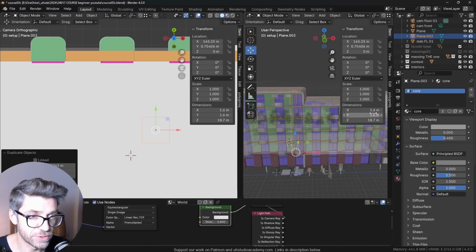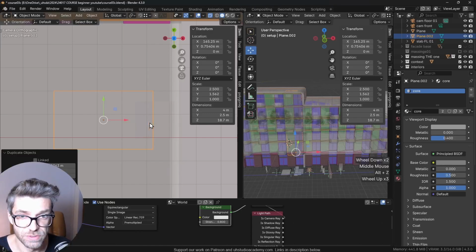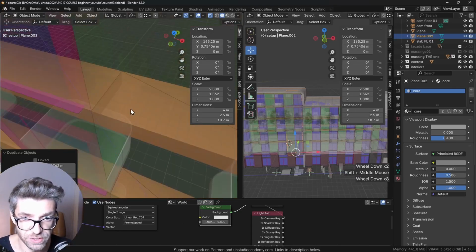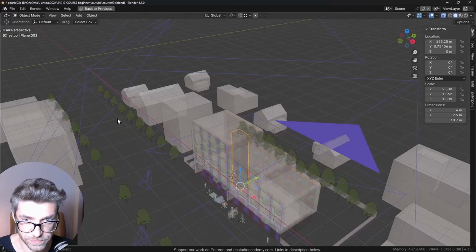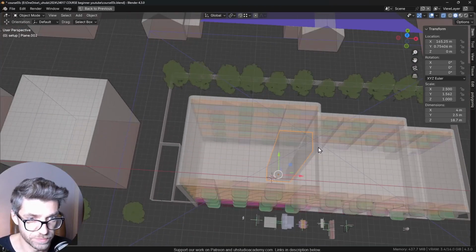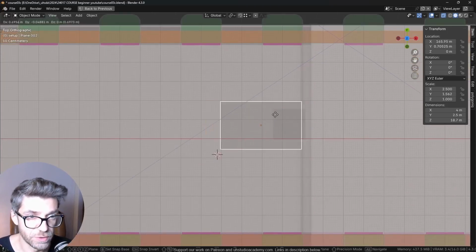That would need to be a little bit bigger. So the Y dimension should be at least 3 meters. Well, maybe 2.5 meters. And the X dimension, something like 4 meters. So that's about the stairs. So we have landings on either side and then stairs about 1.2 meters each on each side. Now let's see where this is lined up. Yep, that's all right. Great. So the stair might come in here like that.